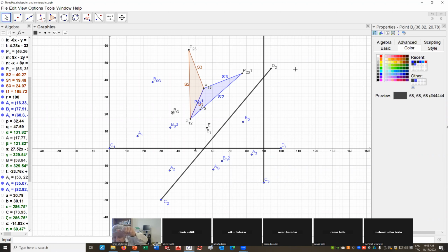Now, fix the coupler, release the fixed link. What are you going to see? That's the inverse motion. Do you agree? I was trying to link this with the triangles, but I think I understand now.